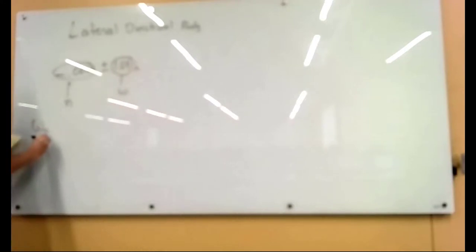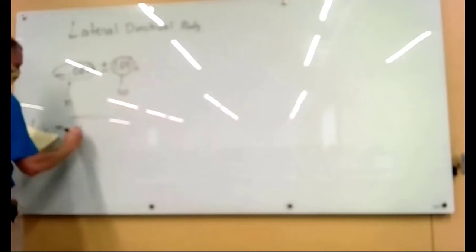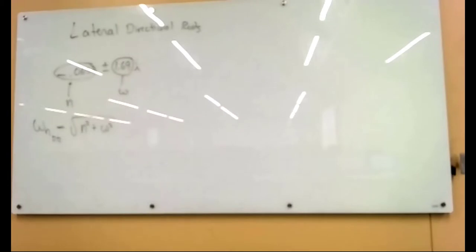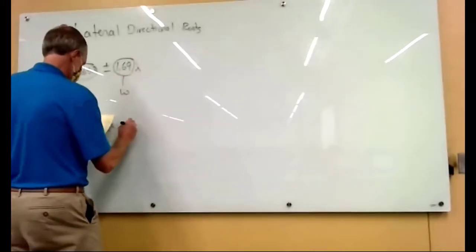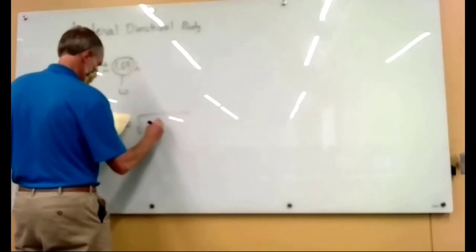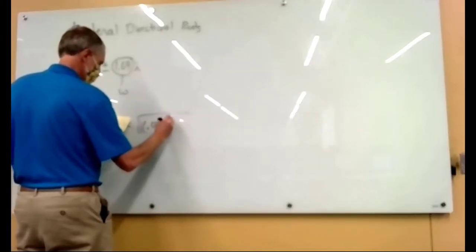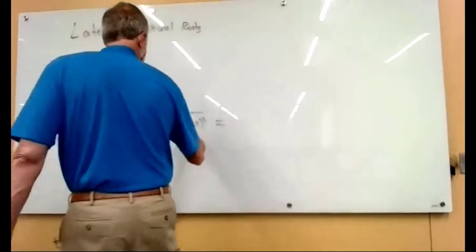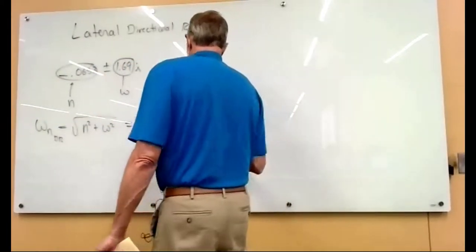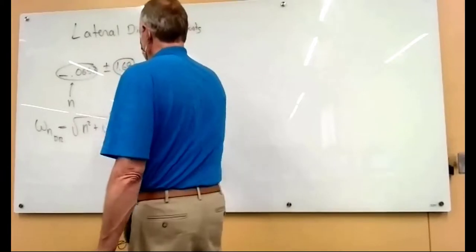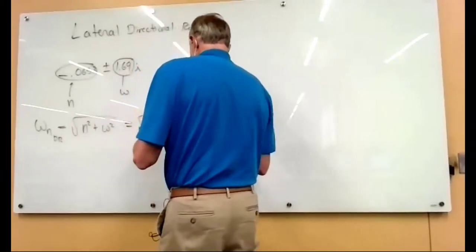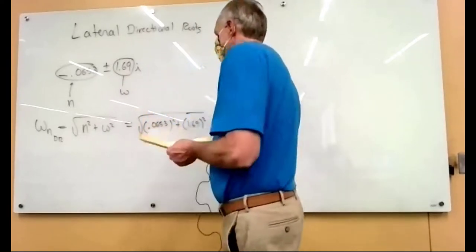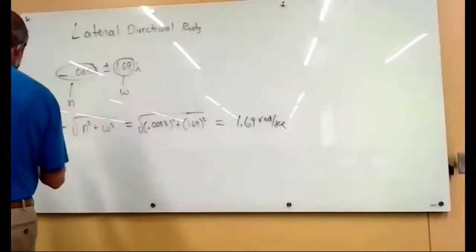So the natural frequency from that formula we did a couple weeks ago is that. So if we plug in the numbers, this one dominates, the imaginary part does. Makes sense because it's the frequency, so it would be a major player, especially if it's not very well damped. So that's the natural frequency, and then we need that to calculate the damping ratio.